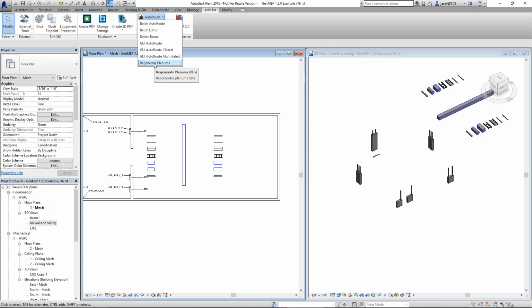This function goes through the Revit model as well as any linked models, which could include other Revit models, IFC format files, files exported from CAD, and point clouds if you're working with LiDAR scans, and stores all that information so that when the routes are generated, any obstructions from the existing models can be avoided. This is what enables the completed routes to be clash-free.